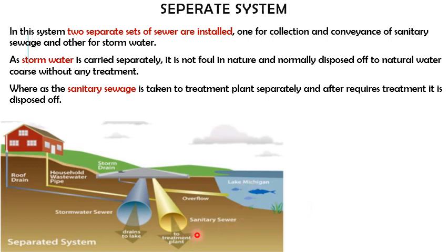That is allowed. Like this, you have to explain the three sewerage systems. Self-explanatory is very easy. One is combined, another is separate. Separate means two excavations are required, two pipelines are required. Maintenance is also very costly. Cleaning of sewers is also another problem. If it is a combined sewerage system, cleaning becomes very easy because the diameter is bigger.